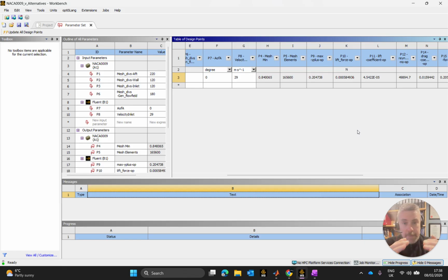So I'm going to be at my maximum speed at that point. When I lose force and I lose thrust, obviously I've lost acceleration, and I am going to start decelerating because of losses, because of two main elements. One is going to be rolling resistance and the friction that comes with that, and the other there is obviously air resistance, which is also another form of friction.